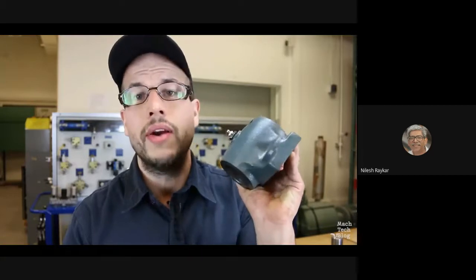As I've mentioned before, there are two main categories of bearing: anti-friction and hydrodynamic. Anti-friction bearings, which are composed of balls or rollers sandwiched between two rings, are often the preferred method of shaft support in modern machinery. They come in many different standardized sizes and styles, and so it's easy to find off-the-shelf replacements for most applications. But where large, heavy machinery is concerned, the hydrodynamic bearing is the bearing of choice. Sure, they're a little less efficient and they have sensitive lubricant needs, but their design is simple. They can handle extremely high loads, and theoretically, they can last forever.